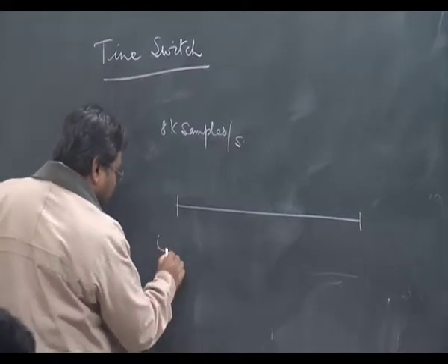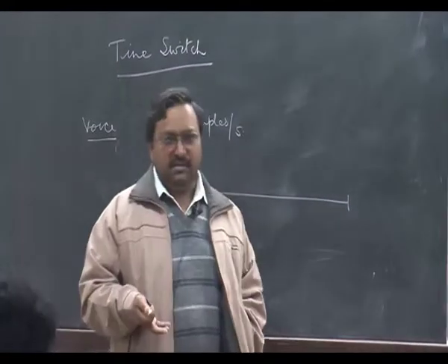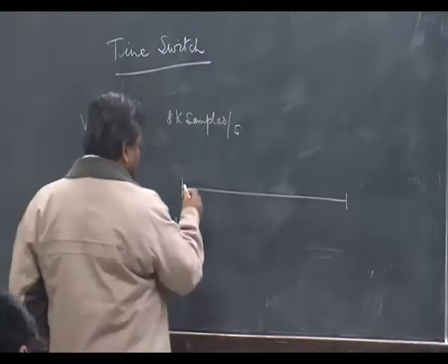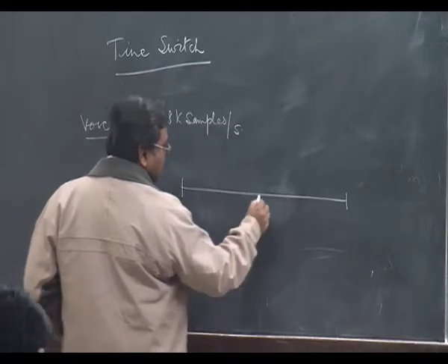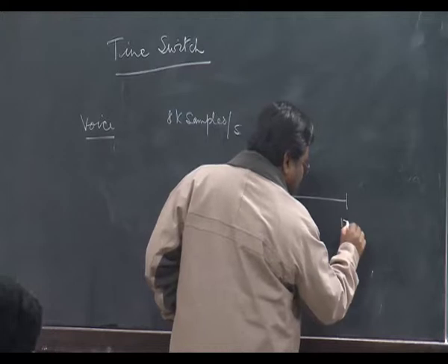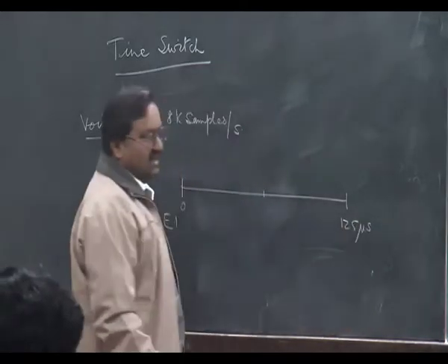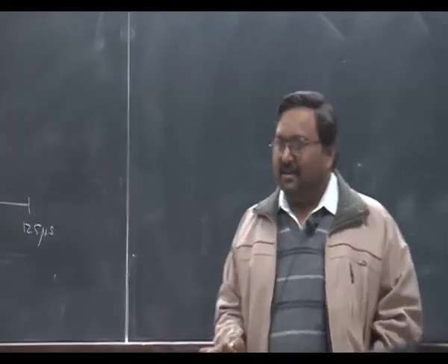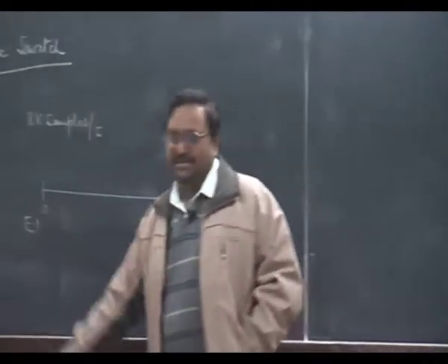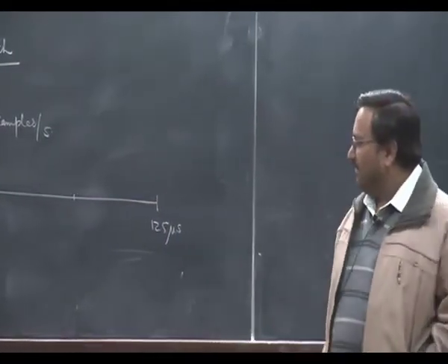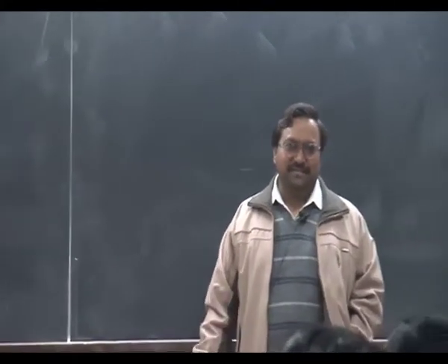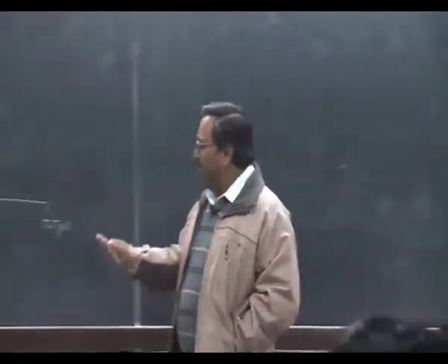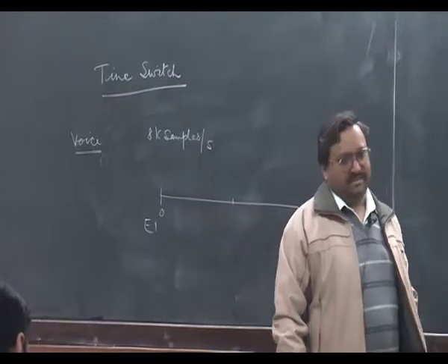One of the examples I had done earlier in the previous semester was the E1 carrier system, and T1 also. The E1 carrier system is going to have 32 slots, and as I have already mentioned in the previous lecture, every framing, whatever is being used anywhere, is going to be of 125 microsecond duration. Everything is of 125 microsecond duration, whether it's an SDH frame, an E1 frame, a T1 frame, an E3 frame, whatever you take. Only the number of voice slots which are transported is going to change.